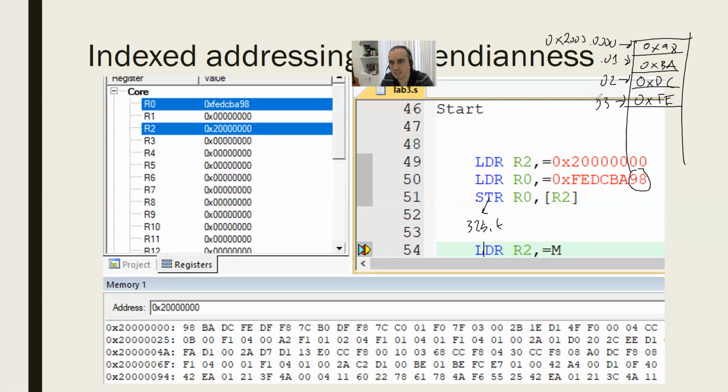So how can you test it in Keil? In Keil, you can read a part of the memory. If you open the memory tab, which I'm going to do in the next hour after we give a break, you write your start address in the memory window. This will show the addresses of the memory. Actually, you can change this configuration. This is the way it shows only bytes, hexadecimal bytes. You can change this. We are going to do this, but don't mind it right now. It's like showing each cell. So guys, the first value is this address.